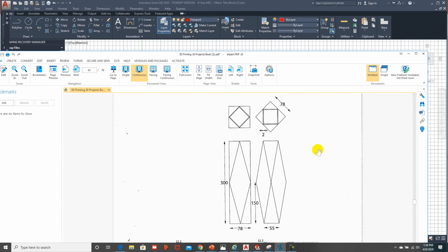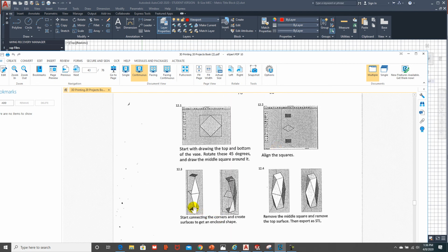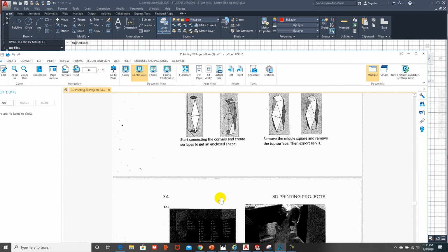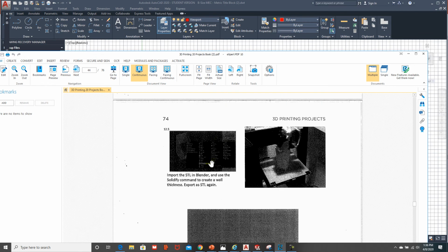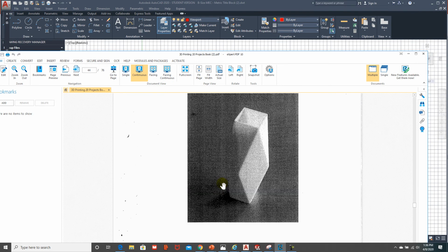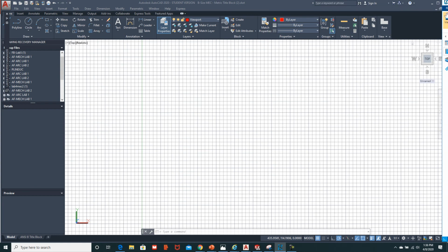So we're looking at a 78 by 78 square, and the author basically does the same technique. He draws these 3D shapes. He uses something like a 3D face to kind of seal this up. That I guess would be how you would do that with SketchUp, and then he imports it into Blender, which he uses to control his 3D printing applications and to print it. So it's a very straightforward example, and I think that's kind of why we chose it, because it allows us to model and then use the 3D printer options, special options, spiralize outer contour.